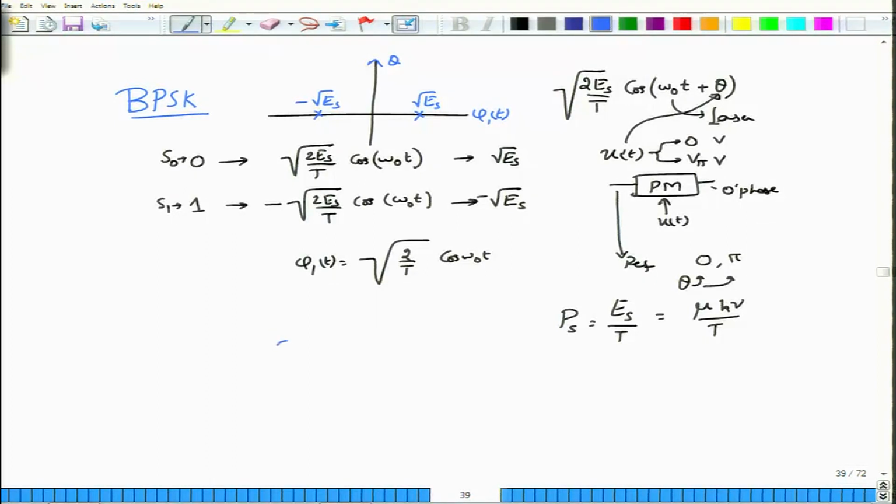Now how do I receive? If you for a moment don't give it a deeper thought, you might think that I can simply put in a photodetector, have a load resistor RL, and then take out the voltage across that load resistor, and I should be all right. Right, that is what you would think. So this is at the receiver after it has come out from the fiber, right? After it has come out from the fiber, the light is incident on the photodetector, and then we hope that the photodetector current IPH, or the photocurrent, would essentially allow us to distinguish between 0 and 1.